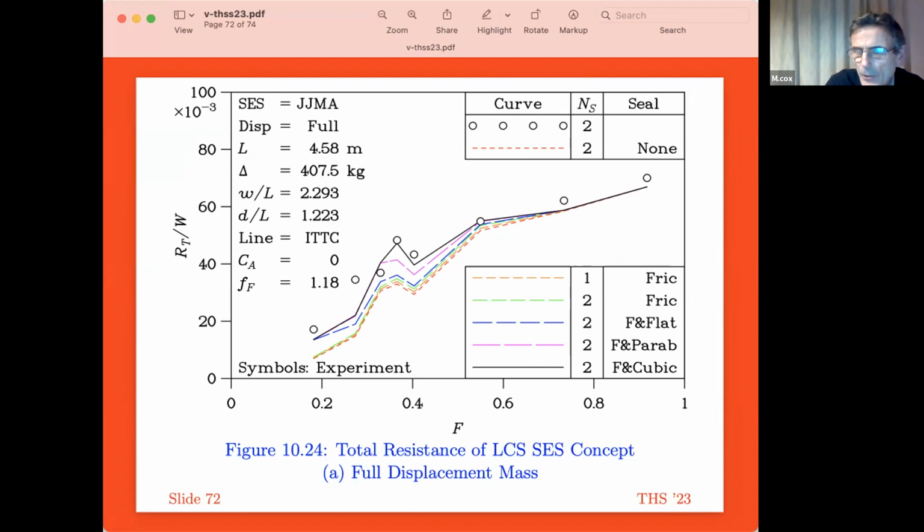I think the breakthrough came from Dennis Bliss, who worked for Hovercraft Development Limited, who came up with the classic finger made of a triangle of material that didn't require any super pressure. It was self-stable. Yes. The crucial feature being a 90-degree bottom angle, which when you unfolded the triangle of material was actually a straight line.